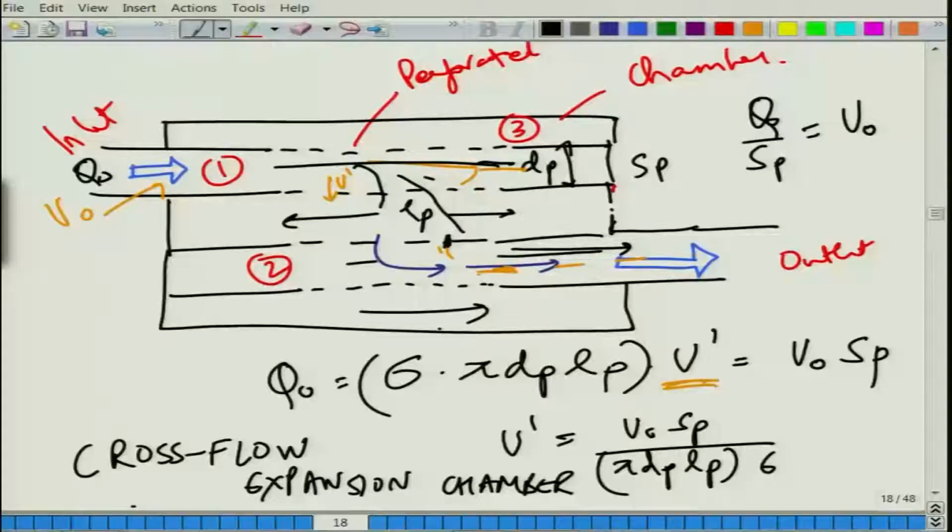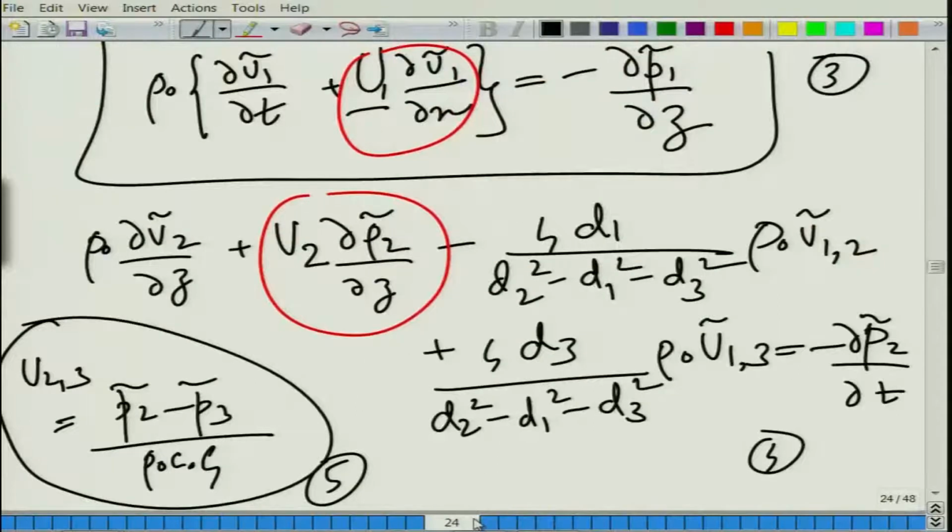So, in our approach we probably cannot take porosity, or impedance, to vary along the length. In all these expressions that you are seeing, wherever we are considering perforate impedance, we are considering it to be uniform throughout the cross section, because porosity is assumed to be uniform and the hole distribution pattern is assumed to be uniform, but it need not be. If it is varying, that is, if we have a non-uniformly perforated pipe, it will have its own effect. For such a thing, we can consider a segmentation approach which will be slightly different.